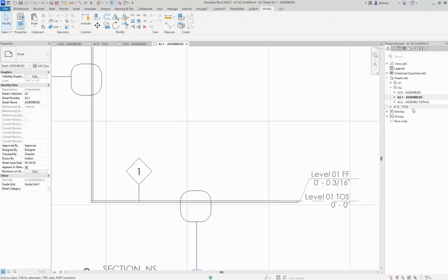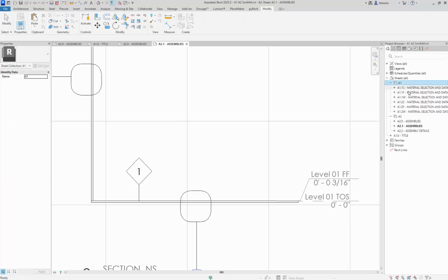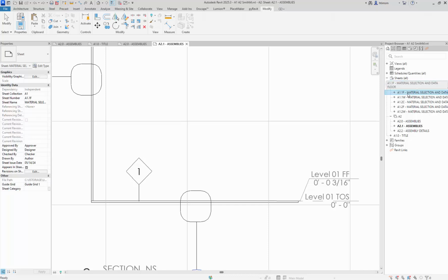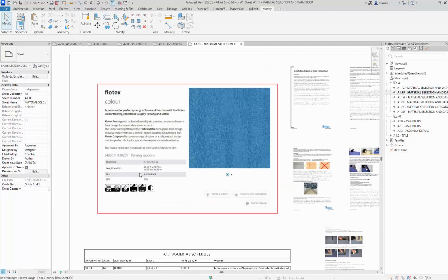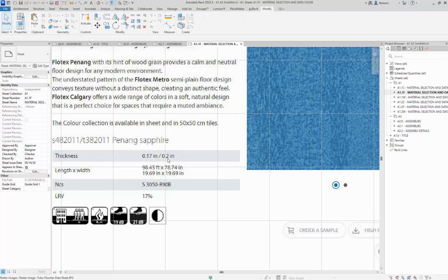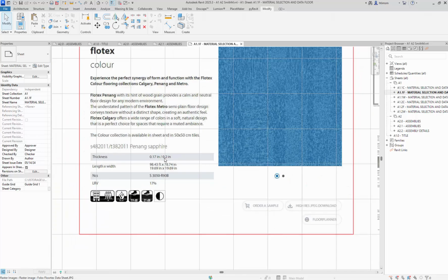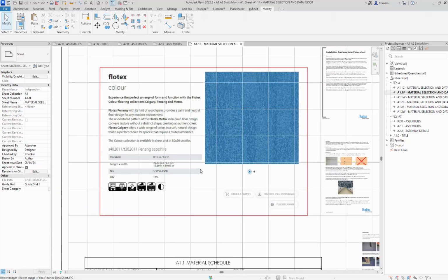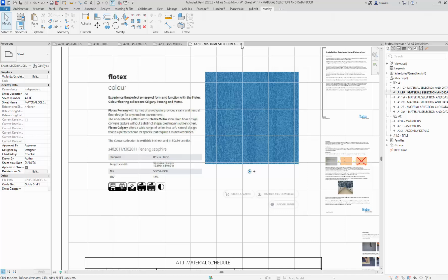So to get the depth of the floor, I'm going to go to my A1 floor, and you can see in here that it's 0.2 inches. And from my installation sheets, they recommend a 1/4 inch backer. And I think that would be nice, especially on a concrete floor. It gives it a little bit more resilient feel. All right, so let's go ahead and get started with that.